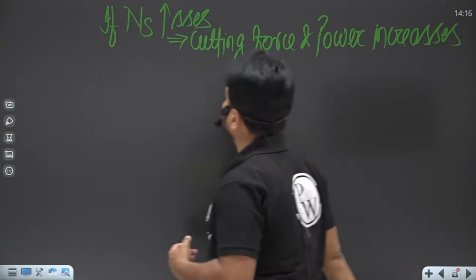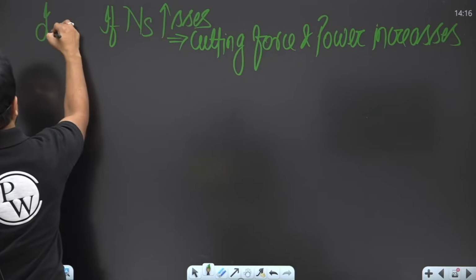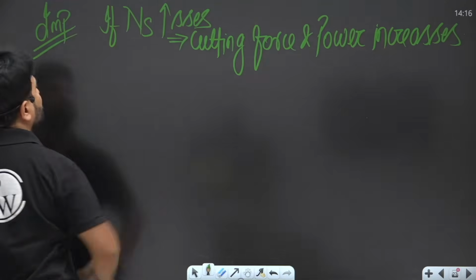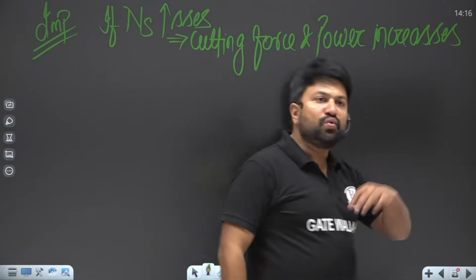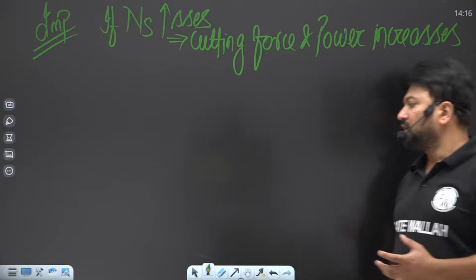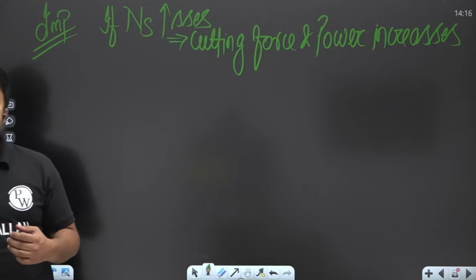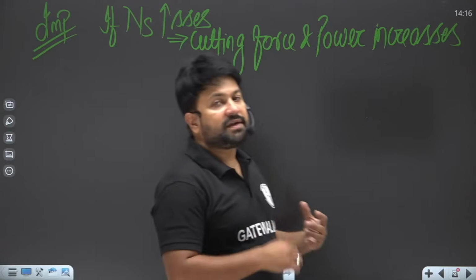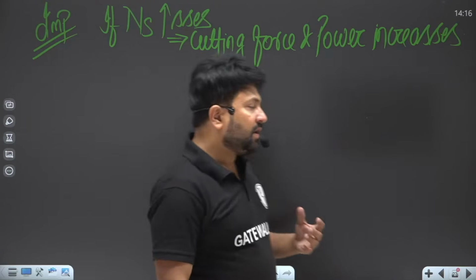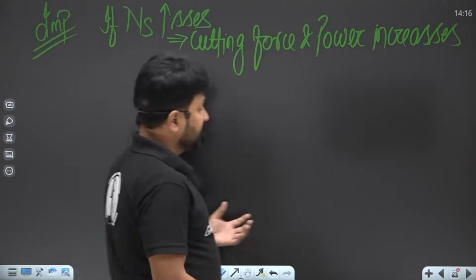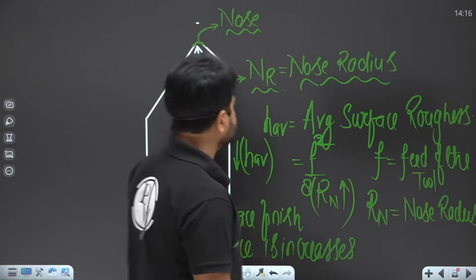This is a very important point from the nose radius point of view. So we have to keep the nose radius in an optimum condition. Otherwise chattering will happen.